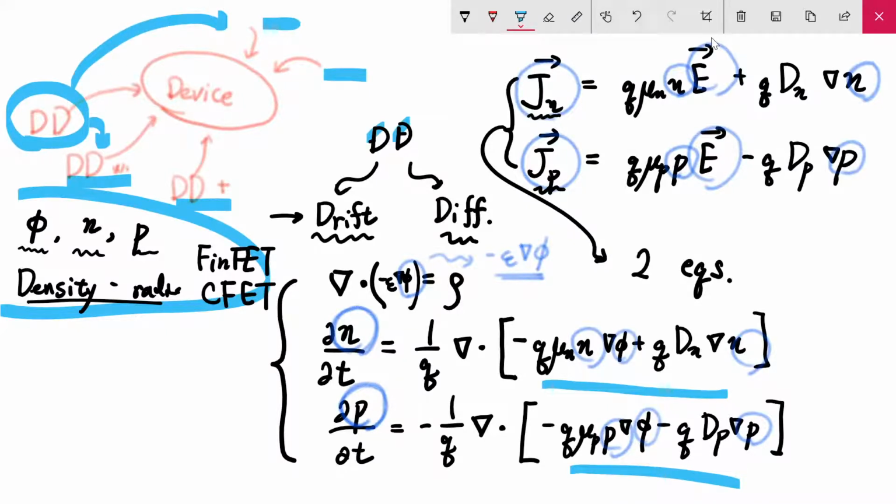Once we solve just the isothermal drift-diffusion model, then we can allow the temperature variation. Otherwise, sometimes the system becomes too nonlinear, and we will have convergence difficulties. So when you start your simulation, you may say, my ultimate goal is really electrothermal simulation, so I will just make a code which is strictly valid only for electrothermal simulation. It is not possible. Even though your goal is ultimately electrothermal simulation, during your journey to that result, in some part you have to do just the conventional, tedious drift-diffusion model.